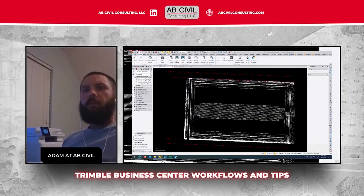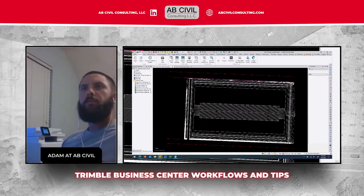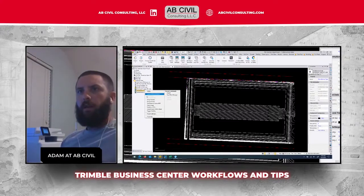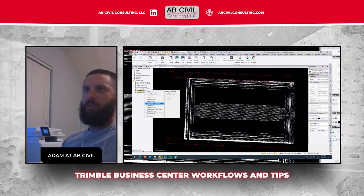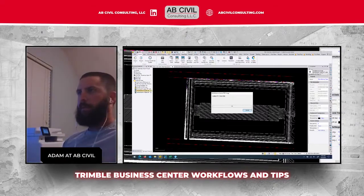So first going to go to my Project Explorer at the bottom. We go to imported files, and I've already got the grading plan imported, so I'm just going to click on this first one, right click it, and then I always do georeference vector PDF. It doesn't actually have to be a vector PDF to work. I always pick that option because it gives you a chance to clip it if you want to.